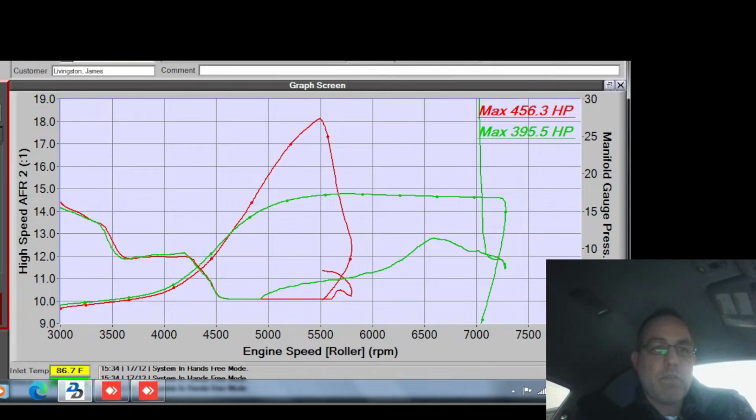Okay, so let's go to that map. Look at that. So volumetric efficiency. I don't have it dropping that hard up there. I'm really surprised it went that lean. Fuel pressure was good though. Fuel pressure was beautiful. What RPM is that showing at? 67. Okay. The intake cams are moving there at 67. And we were at 32. Oh yeah, there's a 6% drop right there. Okay. No, it is dropping fast there.